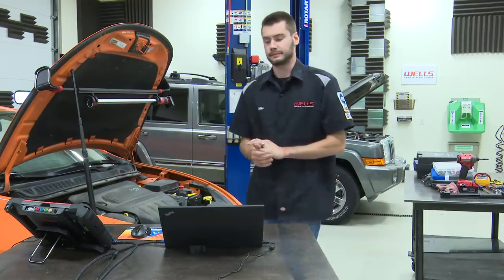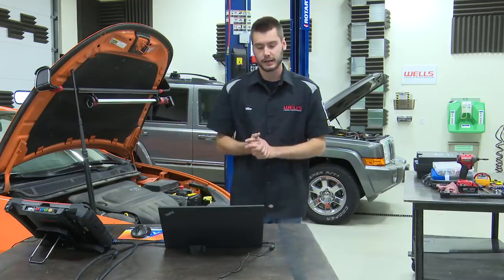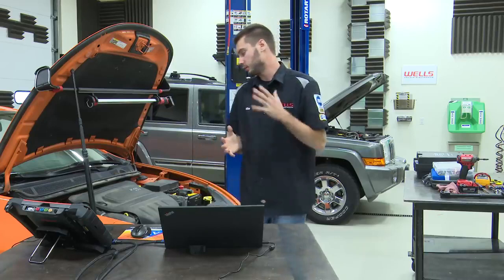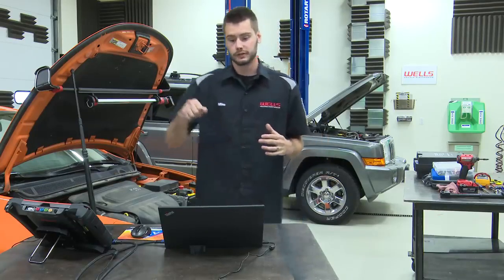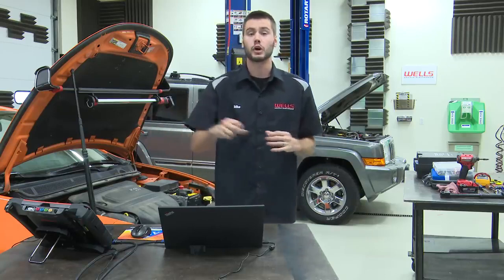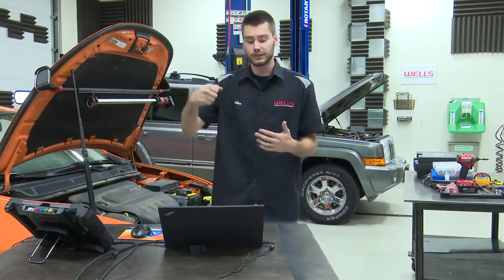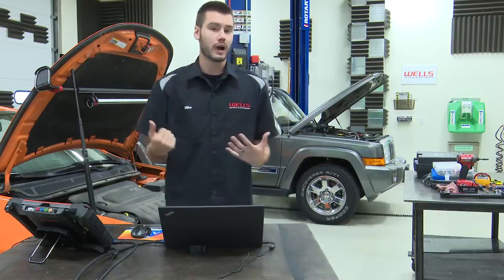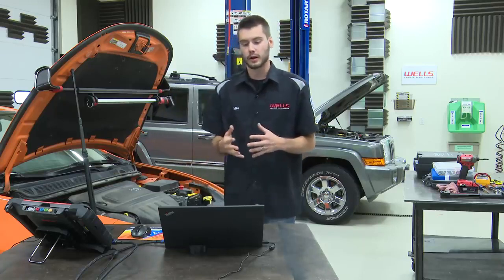The complaint is that every two weeks or so, give or take, this thing would do some weird stuff. The shifter, this is a floor shifter, would all light up red. Normally just the single gear that you're in would be red and the rest of the lights would be white. They would all light up red. When that happens, if you shift this thing down into reverse or into drive, it's a real harsh engage. It slams into gear. It doesn't do what it's supposed to do.